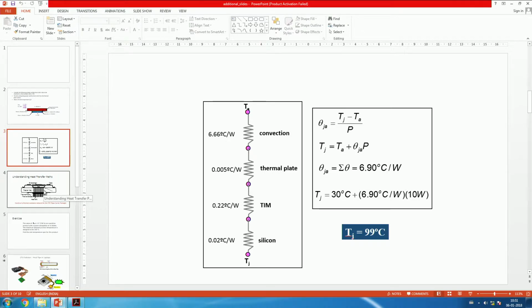So is there a way that some 90%, 95%, or 99% can be taken? That's what we try normally. Whatever we don't, we say that is extra. If something is getting lost from the other sides, it is an extra. I am not going to depend on that. And many a times, especially for pin grid array and all, where the socket is plastic, the thermal resistance to the board is very, very high.